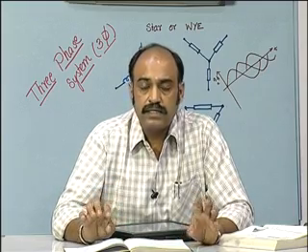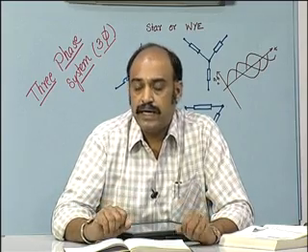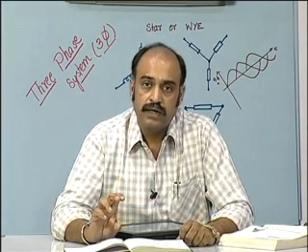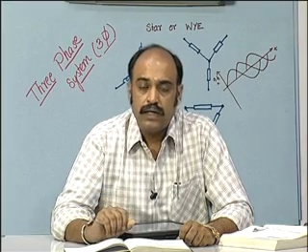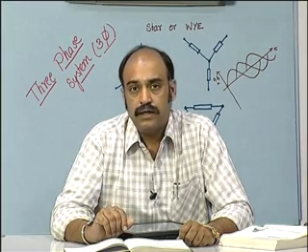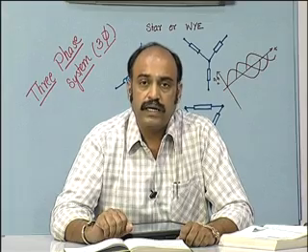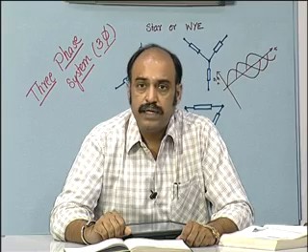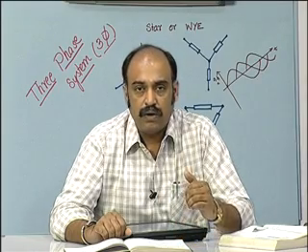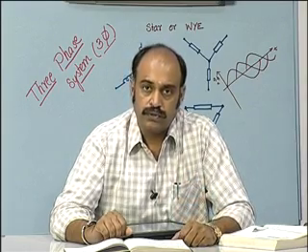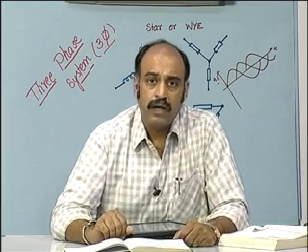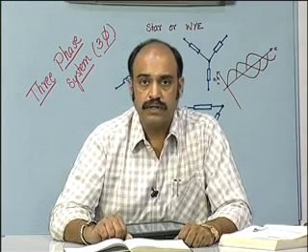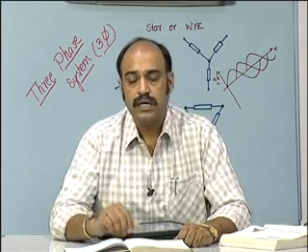This resistance, capacitance and inductance will form a delta, and these phase currents will cancel out in such a manner that there will only be the active component of the current. And on the line side, it will appear as though you have all three balanced currents flowing through it. Of course, one has to be careful in connecting these three components. One should not interchange the positions of these components, in which case you will have an unbalanced situation.